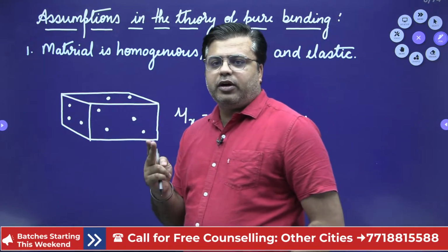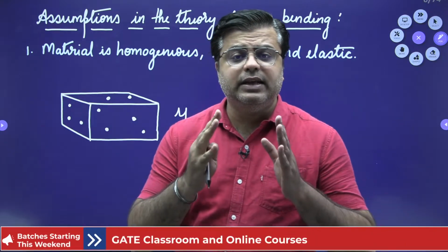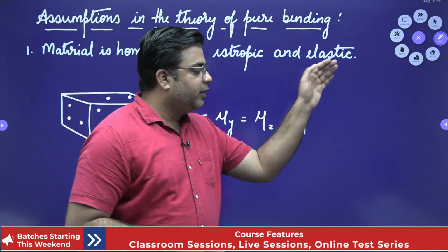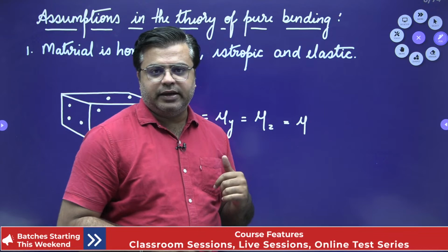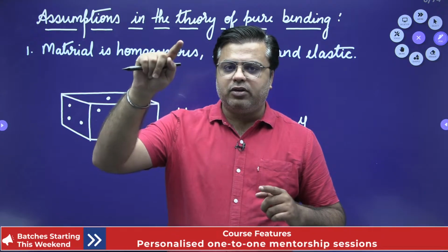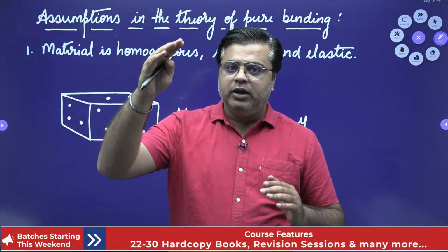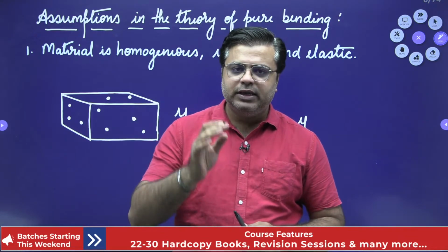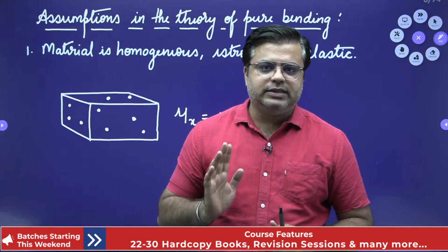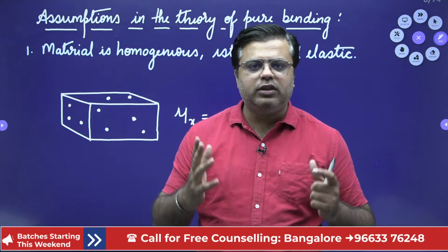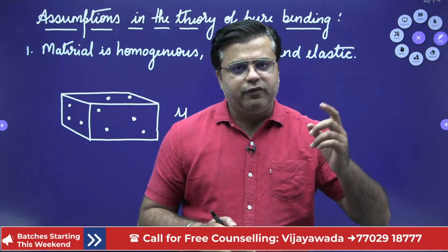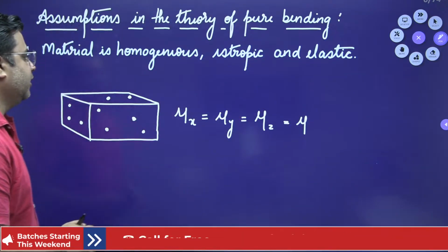Second and the most important point which is listed here, material is elastic, right? So we will be having this entire discussion when the material is under the elastic state. You remember when we draw the stress strain curve, we draw this proportionality limit, then we draw this elasticity limit or elastic limit. So the maximum amount of stress that can develop in the material due to bending will be under the elastic state, right? Means if you just unload the material, it is going to regain its original shape and size. So all that discussion for bending stresses is for elastic material, right? This is the first assumption.